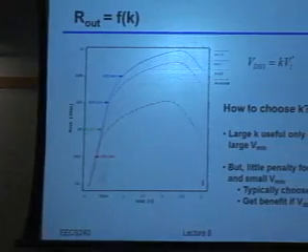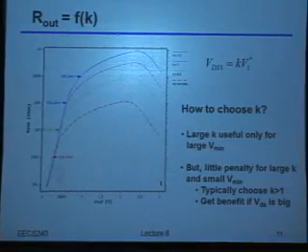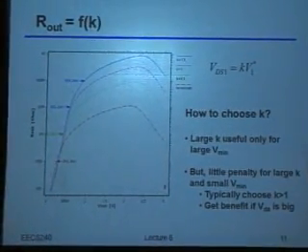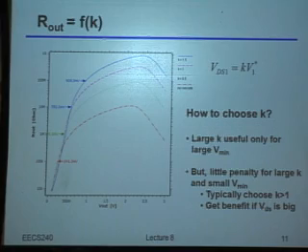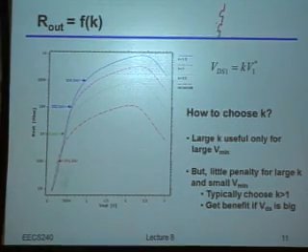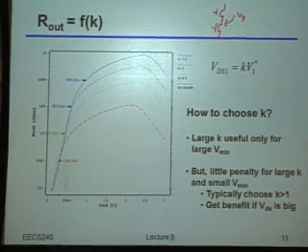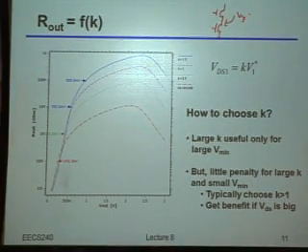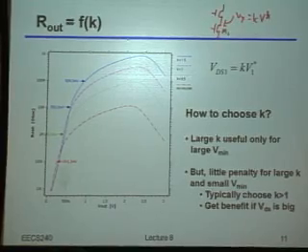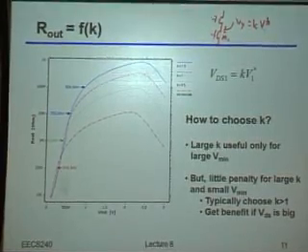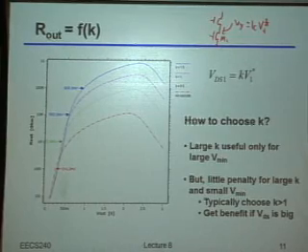So I believe where we ended last time was starting to talk about the output impedance of these cascoded structures. In particular, I asked the question as to what was the best way to choose the bias point of the center node, let's call that Vx, inside of a cascode structure. And we said that we could always set that to be equal to some k times the V star of the bottom device. So let me call M1 the bottom device. That would be the V star of M1.